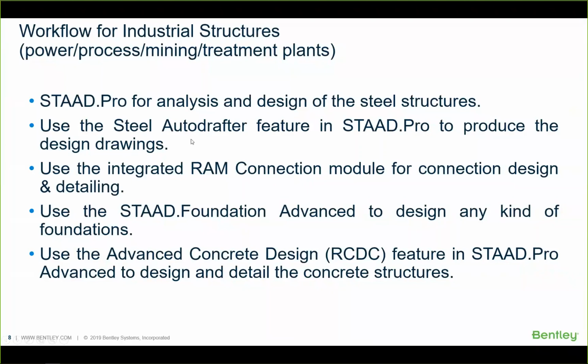And you can save these drawings in a DXF file also. Notice that this is not a complete detailed drawing, but just the design drawing, the general arrangement drawing only. It won't have the connection details. But then we have this RAM Connection program, which is integrated inside STAAD.Pro, even though it's licensed separately. It's part of Structural Enterprise anyway. So this module can be useful for connection design and detailing.